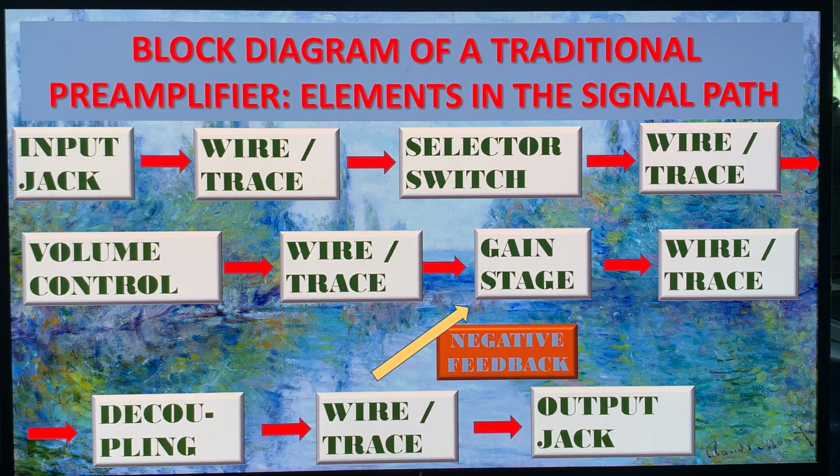If you can bypass the traces, get rid of them, and do hard wiring, there's a huge jump in the sound. And that's what my mentor Stu did, and what I showed on the PV12 preamp that he modified: he was bypassing the traces with hard wires, and that improved the sound tremendously. But this is true for the GET preamp as well.